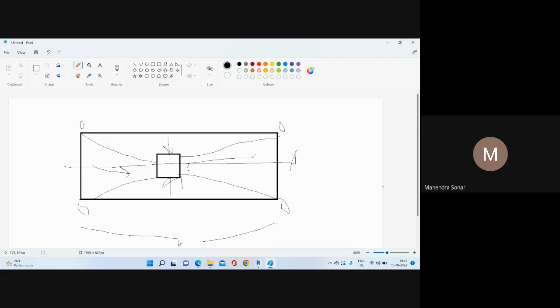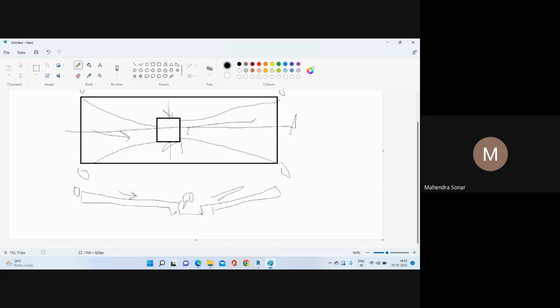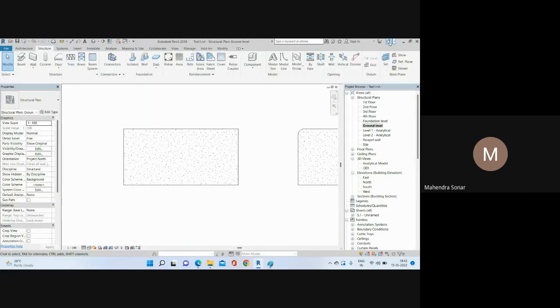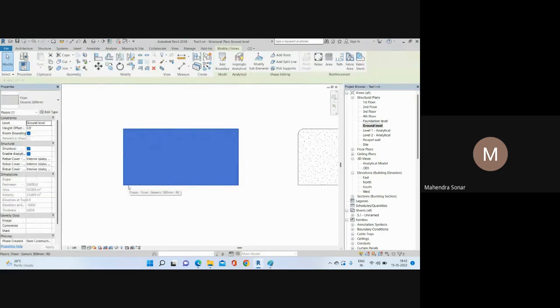And then I want to add some here, like that. So this is my slab thickness and going down, okay, like that. So this is my zero level, and suppose I have given -50 here. Okay, so you can develop or model this slab. Okay, so how to model, let's see. First of all, you should use the floor category, floor slab category. Okay, then you can add the slope here by using this option.